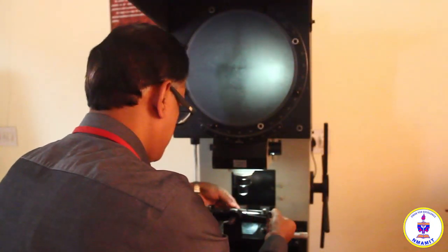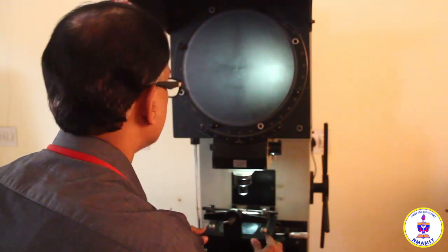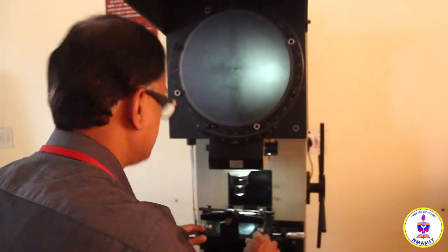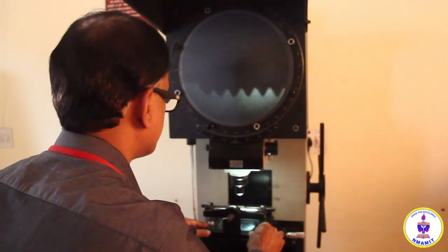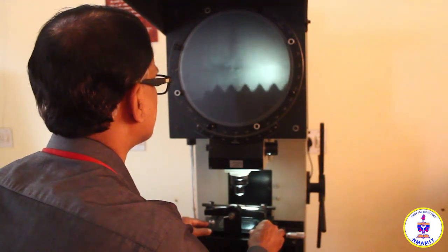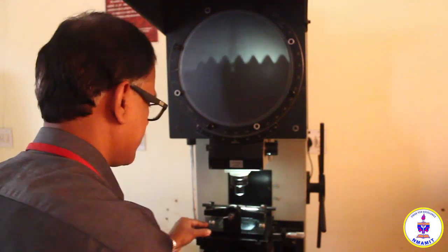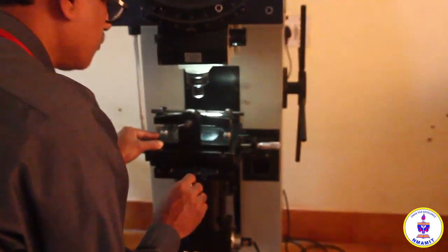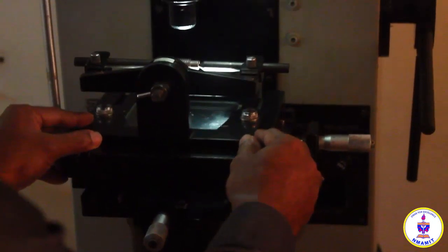Now I have mounted this screw thread within the centers here, but it is not brought to the projector range. In order to position it at the right place, you can move this unit on the table. When it moves here, see the image is coming. It is completely moved. Now to position this correctly for the measurement, the micrometer has only a 25 millimeter range, and this crosswise micrometer is fully closed now. The reading is 1 millimeter. So that is the initial position.